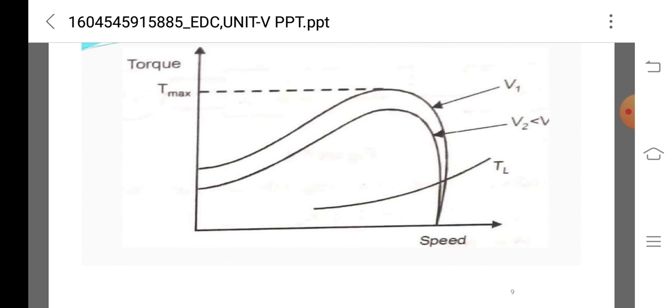In this control method, the frequency of the stator voltage and the poles can be varied, giving, depending on the load: an increase in synchronous speed, a decrease in the maximum torque, a decrease in the starting torque, an increase in speed at the maximum torque, and a decrease in the starting current. Those five categories are shown on this graph.